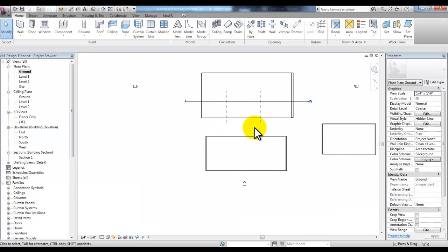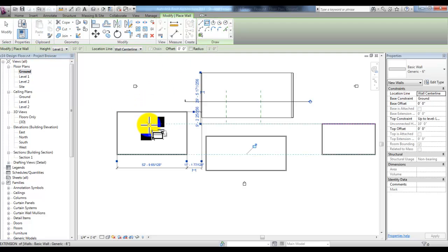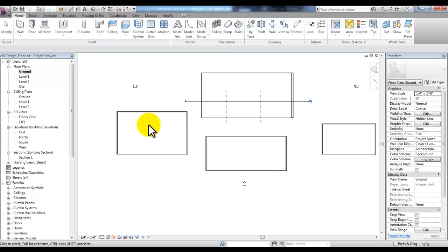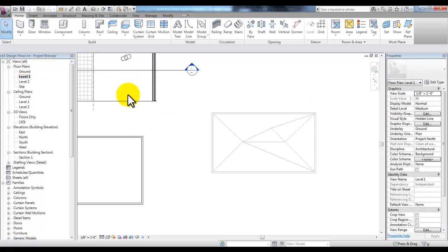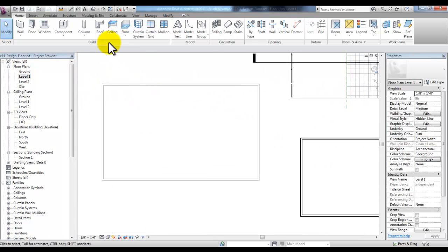We'll create one last building on the ground floor level to level 1 using rectangle so that we can take a look at creating a sloped glazing and a dormer. The first thing we'll do is go to level 1 and place a roof by footprint.